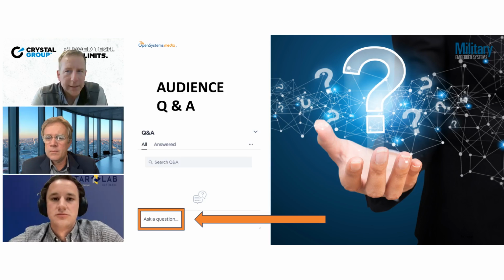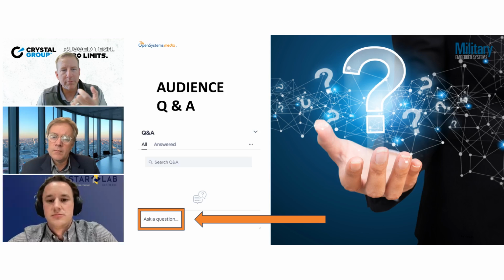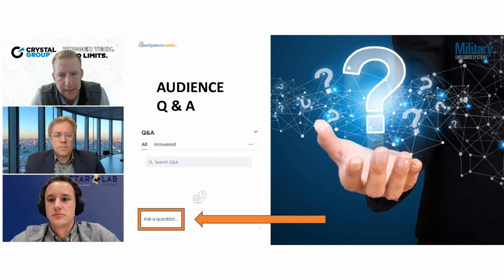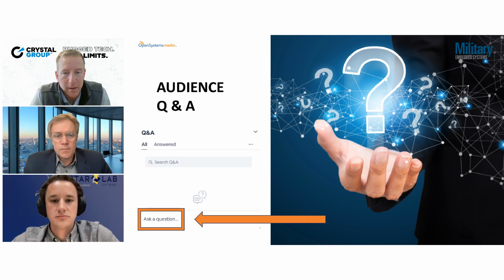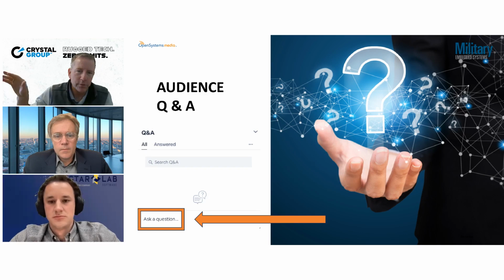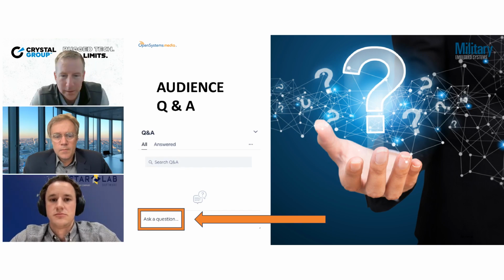This goes back to the conversation of it's always a balance. You're trying to optimize and find that sweet spot of size, weight, and power, processing power, operating temperature, and other requirements. Routinely we're operating at certainly plus 55C. We have seen and fielded some things at 60 and 65C. You start getting up to 75 and 80 and 90, and it just becomes a cooling problem, because the thermal's got to go somewhere. That elevates it to more of a platform question: where can we move this heat and get it away from the box, and it's got to go somewhere that probably isn't 90C. So there's your answer, which is probably more of a non-answer.